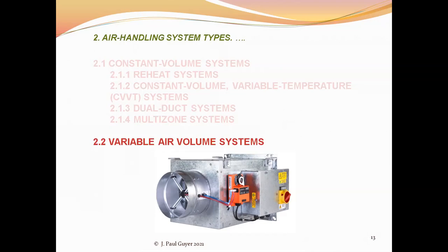And in designing a VAV system, one of the things that has to be kept in mind is you can't and don't want to shut off the flow of air to one of the spaces for temperature control purposes, because you have to have some certain minimal amount of air being delivered to the spaces for air quality purposes.